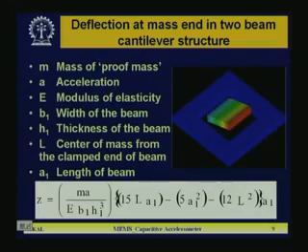So, we thought of a different structure, which is the double flexure, the cantilever structure. Here, instead of one, we have used two flexures. Under that condition, if you move along the y direction or x direction, this whole seismic mass will not rotate along that direction.